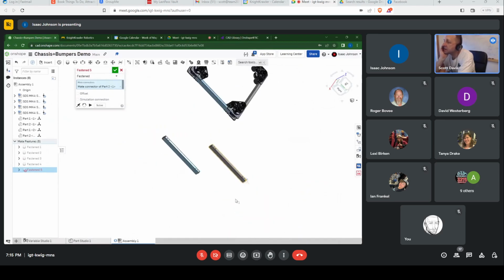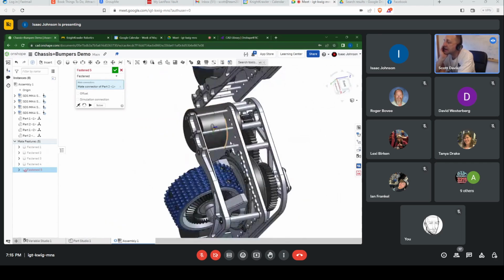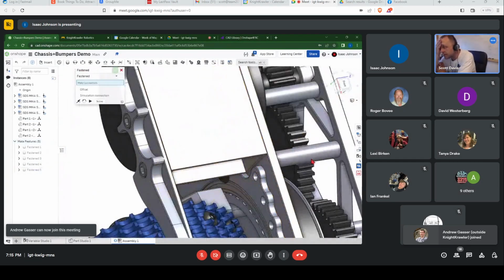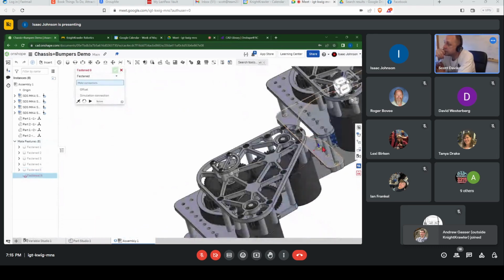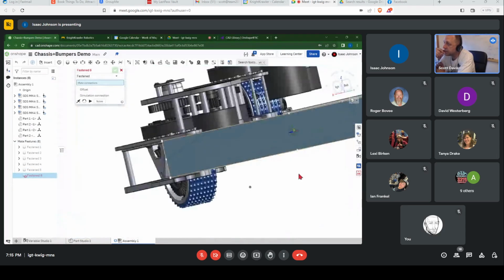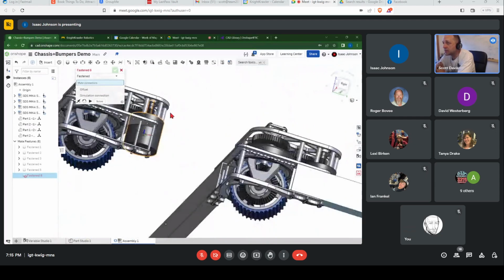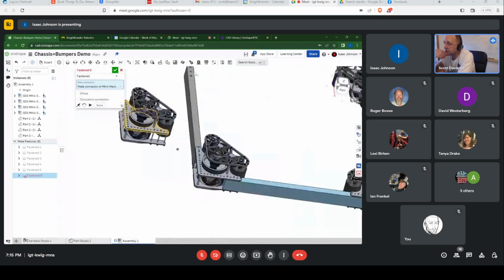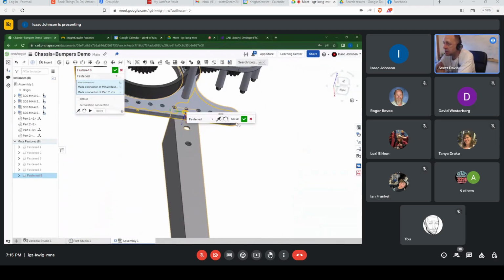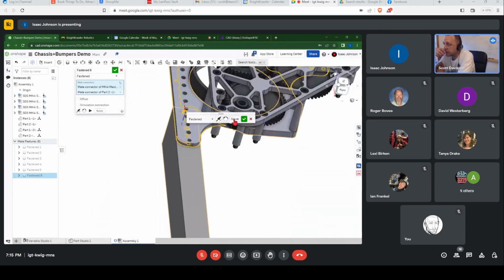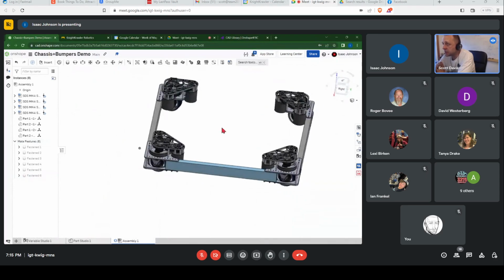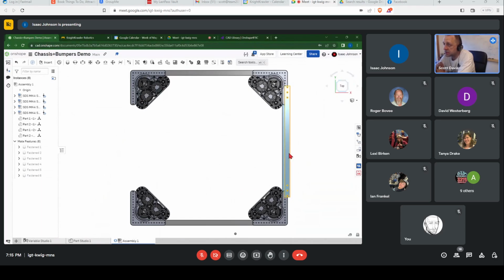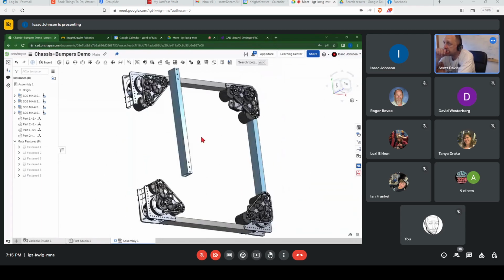So as Isaac is doing this, one of the things that I found tricky when I was first starting on this CAD was especially mates. Doing mates in the assembly takes a kind of special spatial brain pattern, which you can see Isaac has done a good job of developing here. But you can also take these parts and just slide them around and rotate them around the model and get them close. And that can also make it easy to get the mates that you want lined up properly. So in this case, he's taking the circular part of the hole and he's identifying the face that's going to touch the other face's circular part of the bolt.